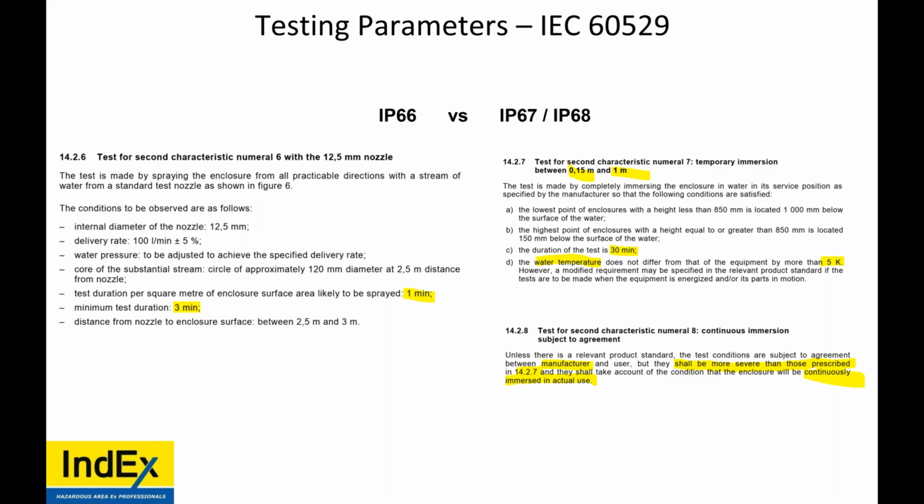Now, if it's inside or outside, if an enclosure is IP67 and it has a hole cut out, that's not IP67 anymore. It would seem to have been modified. For it to be IP67, the gland definitely has to have a threaded entry, specifically because of the immersion, okay?